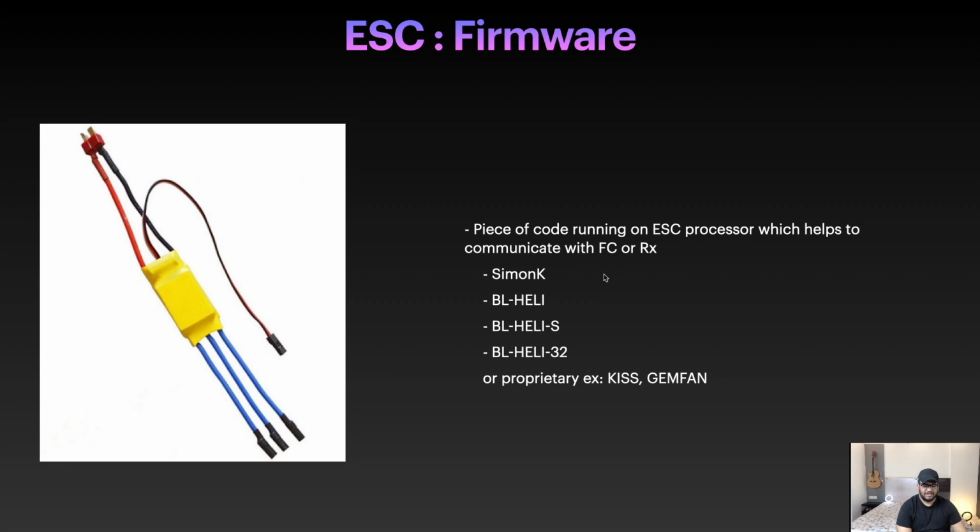By the way, no one uses SimonK anymore. It's quite old. So if you're buying an ESC for drone racing, make sure you go for BLHeli_S or BLHeli_32. These are the latest firmware for your ESCs.